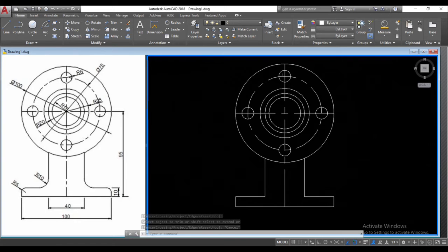All we need to do now is just to put in our radius or curves here. So we're going to use the fillet tool that we learned about. So these two radius would be 5 and these two will be 10. So I'm going to do these two first. So let's choose fillet and then click radius.